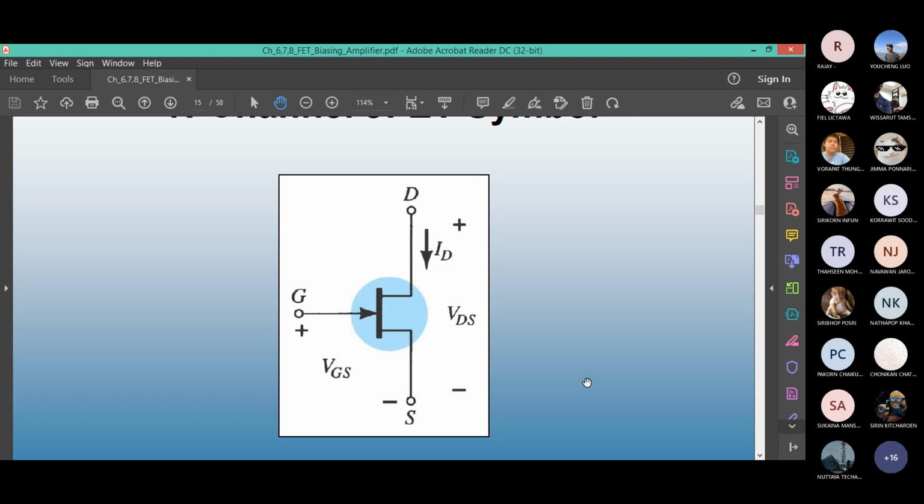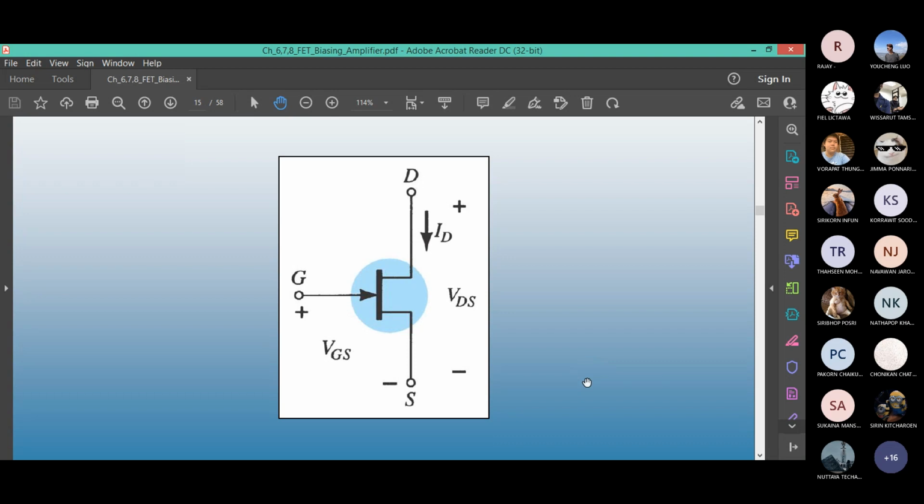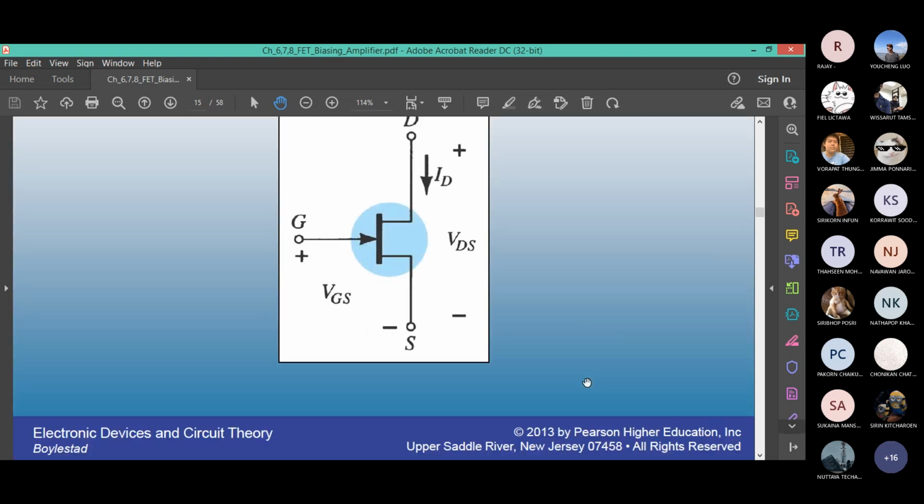On the input side of the JFET, there's a high impedance by nature. So IG is negligible. You can ignore it, say IG equals 0. Student: Do we always ignore IG, or sometimes? Teacher: Always. IG equals 0. So when we have done a few problems in the class where you had a gate resistor RG and the voltage drop IG RG, since IG is 0, we replace the RG with the 0 voltage drop or short circuit equivalent.